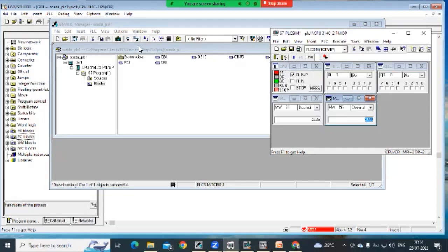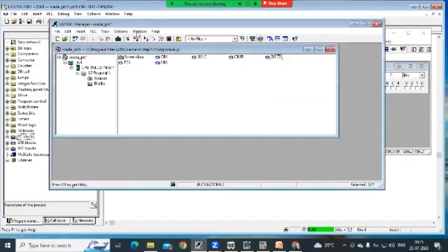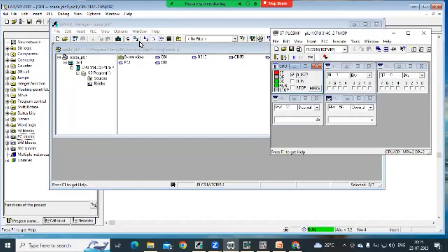Now it is still in stop. Okay, so I need to refresh it. So I just put this to stop and run again. Now you can see the status. It is in run mode, but still it is showing the SF LED. The CPU is in run mode, but still it is showing the SF LED. If this OB121 is previously downloaded, okay, initially if it is downloaded, and if this error occurs, the CPU will show this status only. Okay, SF LED red and run status.